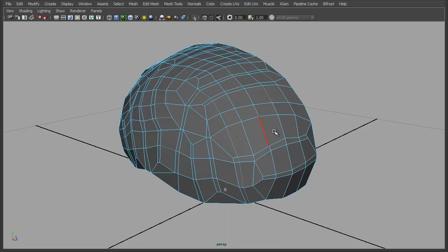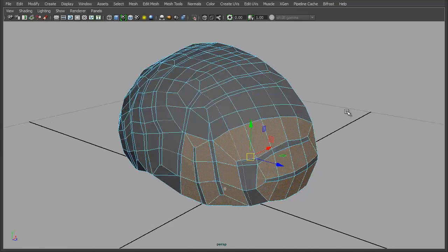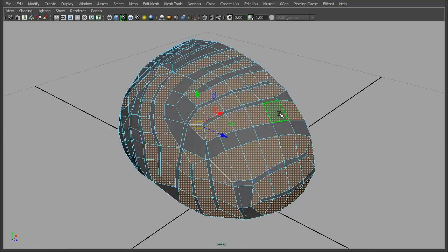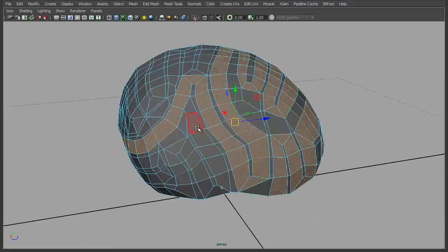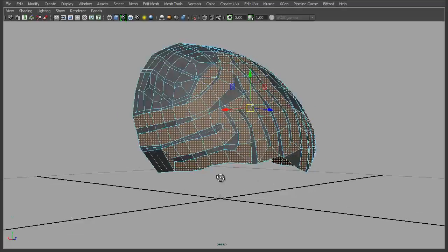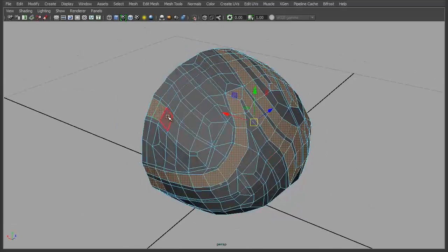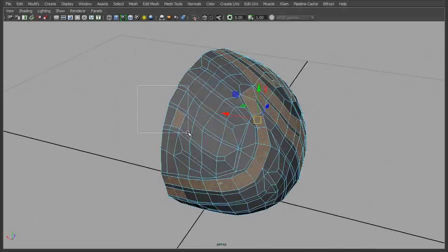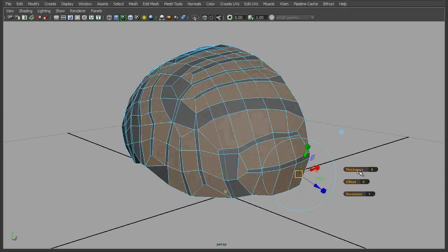What we're going to do though instead is we are just going to select the faces. So in this instance, just click, double click. Up here we'll do the same, double click, so we've got that edge flow around there. See if there's any more where they're not connected. Maybe this one. Nope. Okay, what I'll do is I will just do these two for now, and we're just going to use extrude face.